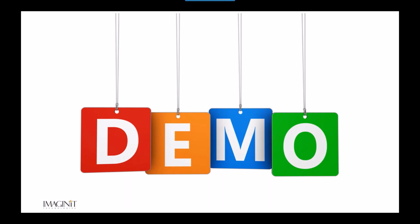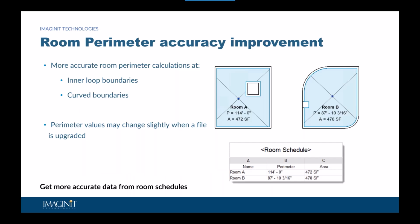For my next demo, I'll be going over room parameter accuracy improvements. We will cover the room parameter accuracy improvement. This new method used to calculate room parameter values has been updated in Revit 2025, resulting in improved accuracy by accounting for inner loops within rooms, in addition to enhancements for calculating the perimeter of round rooms or rooms with arc segments. Users may notice changes in room perimeters when a project is upgraded to 2025.